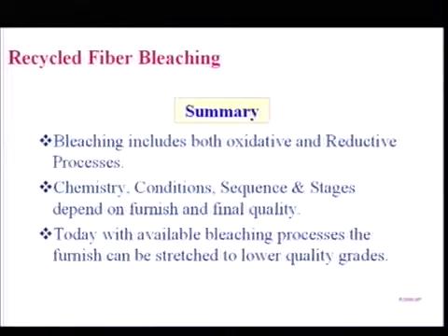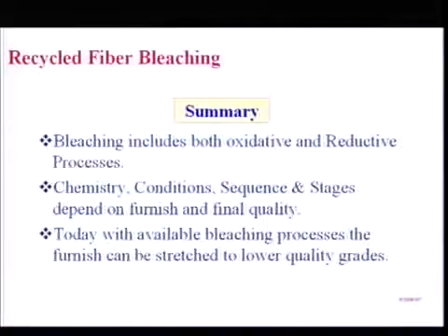Are you starting with news magazine or are you starting with mixed office waste? Do you need 58 brightness or do you need 85 brightness? So depending upon that, you employ brightening chemical or decolorization chemical. Today, with the available bleach technology like peroxide, hydrosulfide, FAS, direct borohydride injection process, with multiple reductive species, you can handle lower quality paper grades, still get much higher brightness for copying paper.